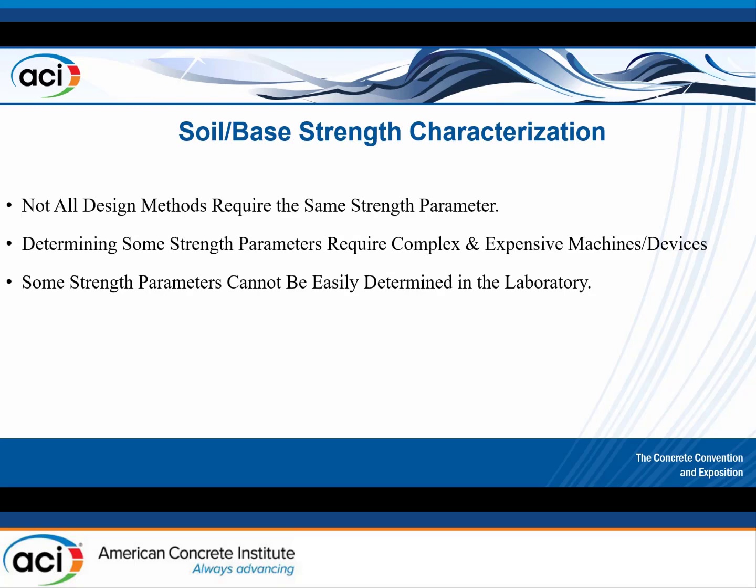When we talk about soil and base characterization, depending on the design methodology you use, it could be asking for a different subgrade strength characterization. Some methodologies may ask you to input the resilient modulus of a soil. Others may ask you to put in the K value. It just depends on the methodology that you're going to use.